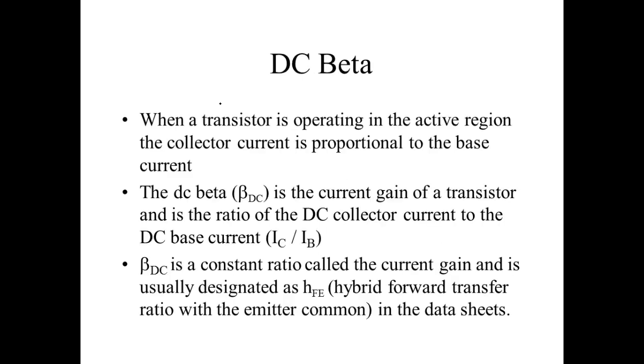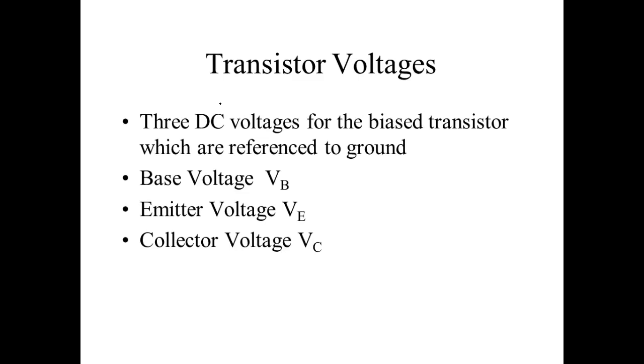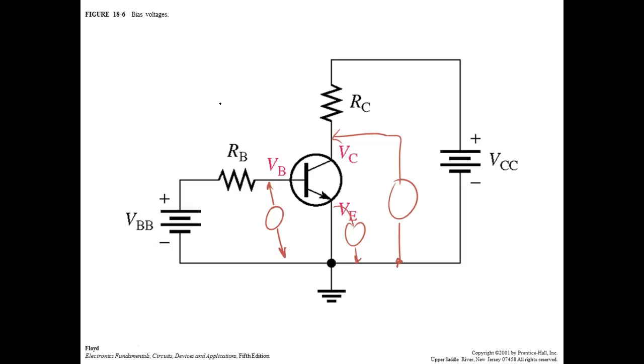Good point though. What else do we need to know about the transistor? We need to know the beta of the transistor. Where am I going to get that information? Data sheet. So I go to the data sheets and look at what the beta was. Let's say I had a beta, just for practical purposes, so I think it's going to saturate.